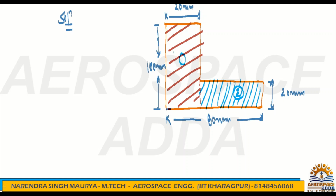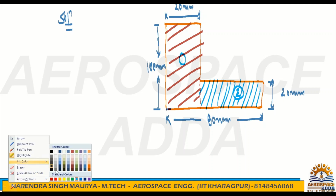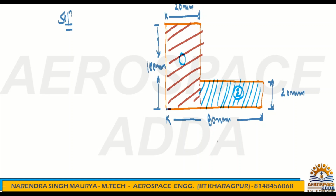All the dimensions have been given. Obviously, this is also 20 mm. So what is the section 2 part? This is 80 minus 20, that means 60 mm. Good. So for section 1, what is the area A1? 20 into 100, 2000 mm square.